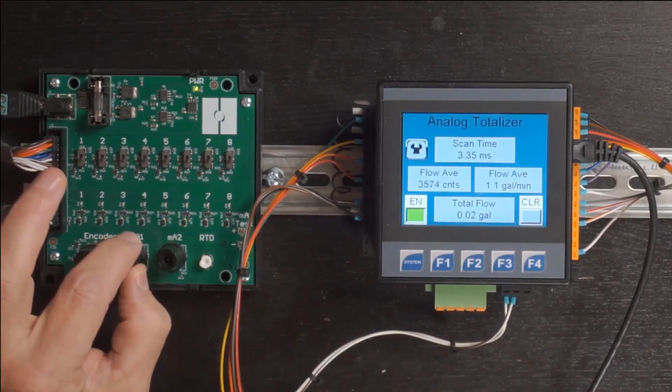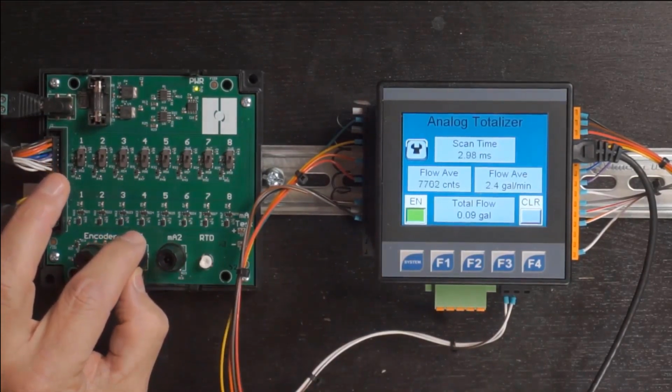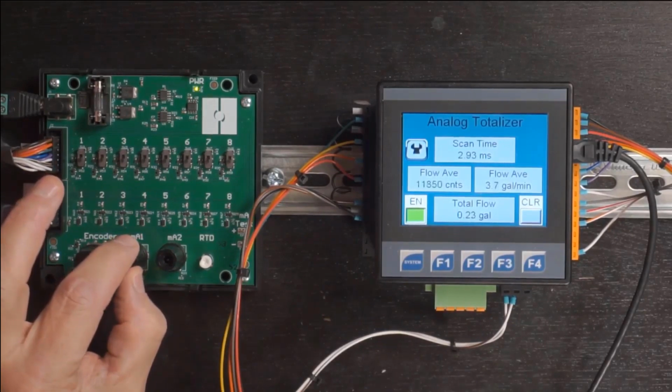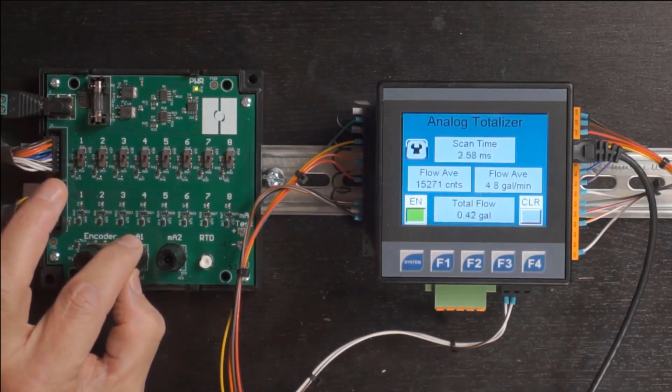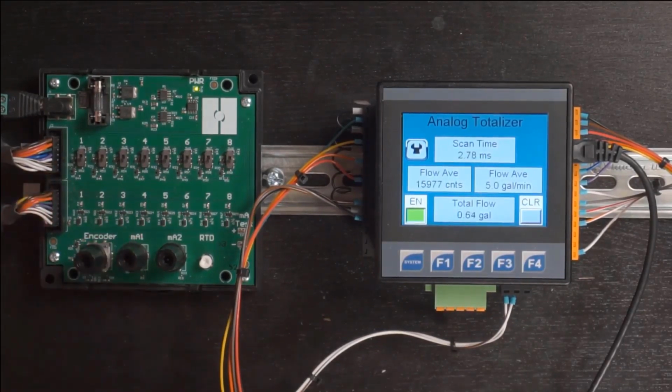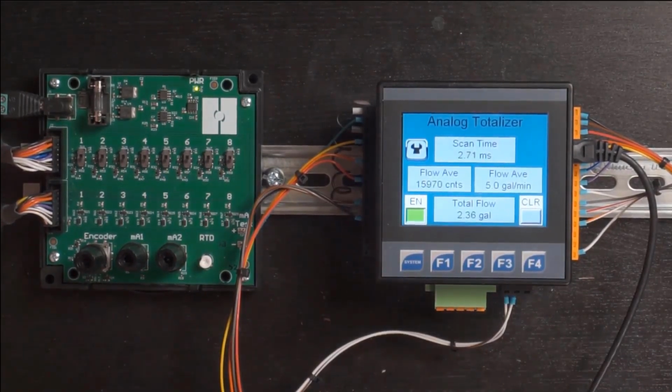And you can see that the flow average is around 5 gallons per minute. And our total flow accumulator is moving up, totalizing and counting the total gallons of water in the application. So that's what's involved in doing analog totalizing with an OCS. The next thing we'll look at is taking a user-defined function block and utilizing that instead of doing the logic programming. To make things easier, we've created a user-defined function block that allows you to just drop into your application without going to all the effort of creating one.